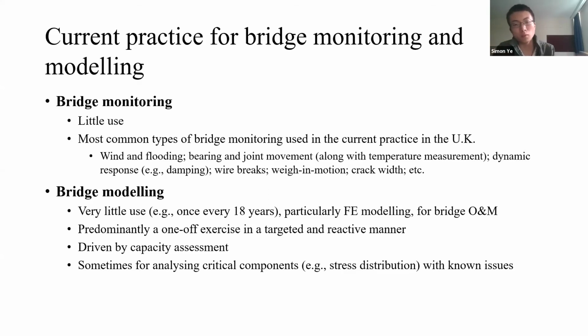Basically, if they're worried about certain components, let's say a joint, they want to make sure that joint is not overstressed. So they do an FE analysis to look at the stress distribution of that component to see if that joint or that component is safe or not.